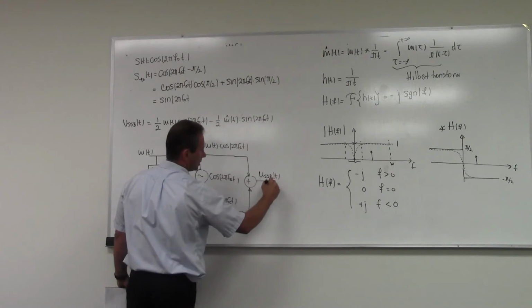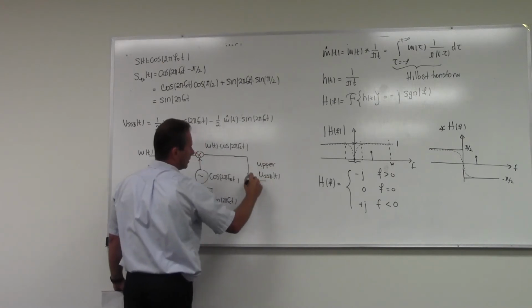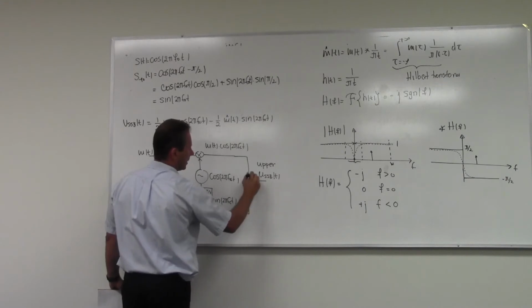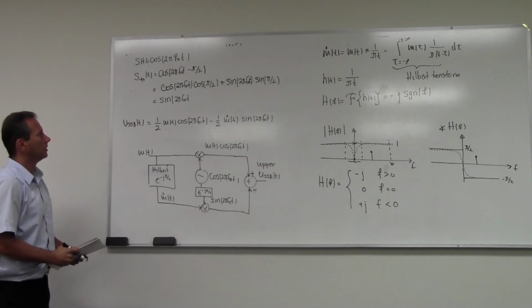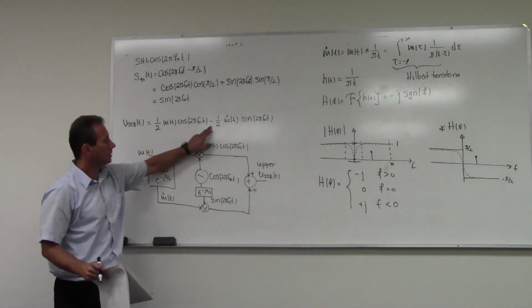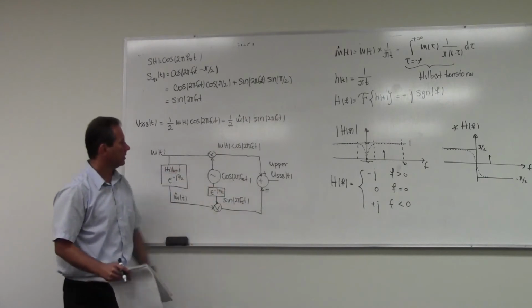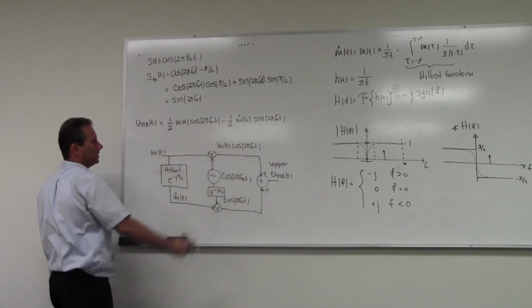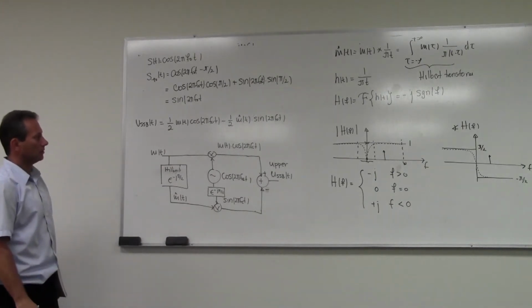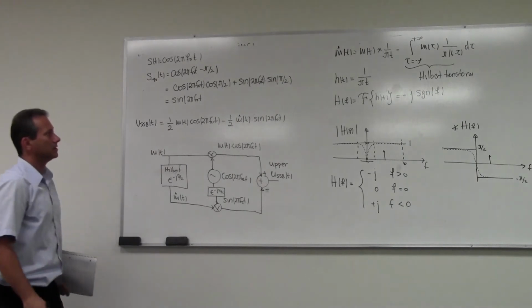This is, of course, the upper. If you want to have a lower, then you would have plus on both sides here, adding these two components. If you want upper sideband, then you take this one with positive and this one with a negative. There is a scaling factor 1/2, but that's not really relevant, because you still have to amplify and transmit it and so on.